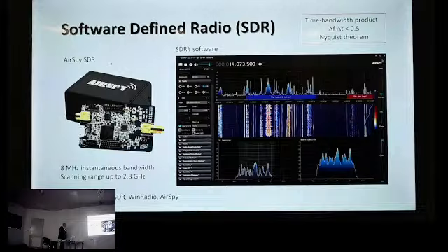Basically, these devices take an input from an antenna, and then you connect that to your computer, and you can display a spectrum of the radio emission. In this case here, this is what's called SDR Sharp software, and it's showing you what's called a waterfall display, frequency across the horizontal axis and time running down that way. It's like water falling down through a waterfall, and in this case, this is looking in the shortwave band at some of the shortwave stations.